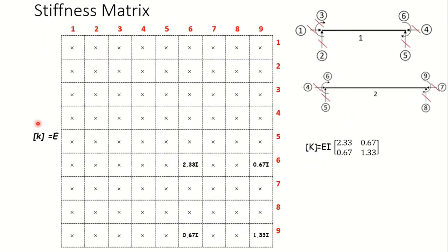And now we'll come to this global stiffness matrix of the beam K. So when the three displacements have been arrested at joint 1 or at end A, I have to delete first row, first column, second row, second column, third row, third column. So all these elements will be gone. Since no displacements are allowed over there, we are not interested in these stiffnesses also.